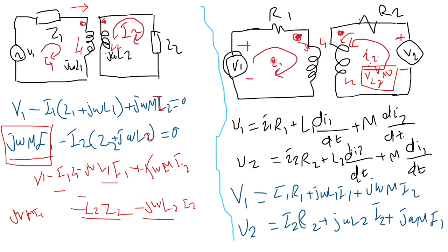Again, I have L1 and L2, and I have the dot convention like the figure shows. So I can see that I1 enters L1 at the dot, and I2 enters L2 at the dot. So both currents enter the coils at the dot. So this means an aiding connection case, which means that the self-induced EMF and the mutually induced EMF have the same polarity.